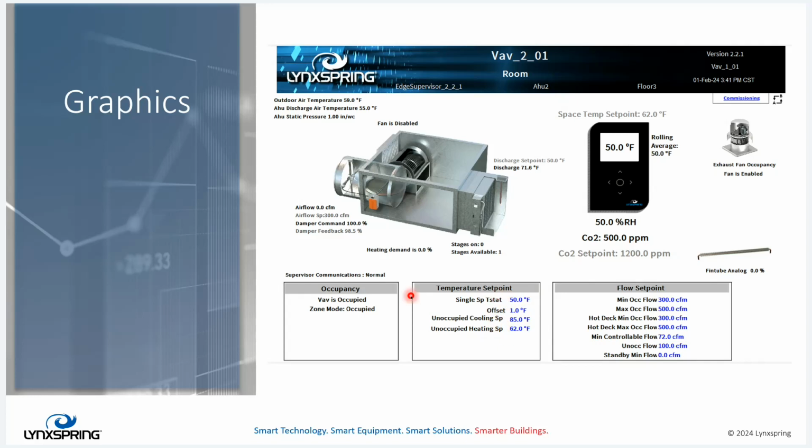Okay. You can decide for yourself whether you want the set point to come from a digital stat, or you can choose to set it up so that you determine what it is using what's called the graphics set point, and you're just right clicking on these to access those specific types. If you choose a global, which is the other option, there are pre-built set points. I think, excuse me, at 74 degrees cooling and 72 degrees heating.